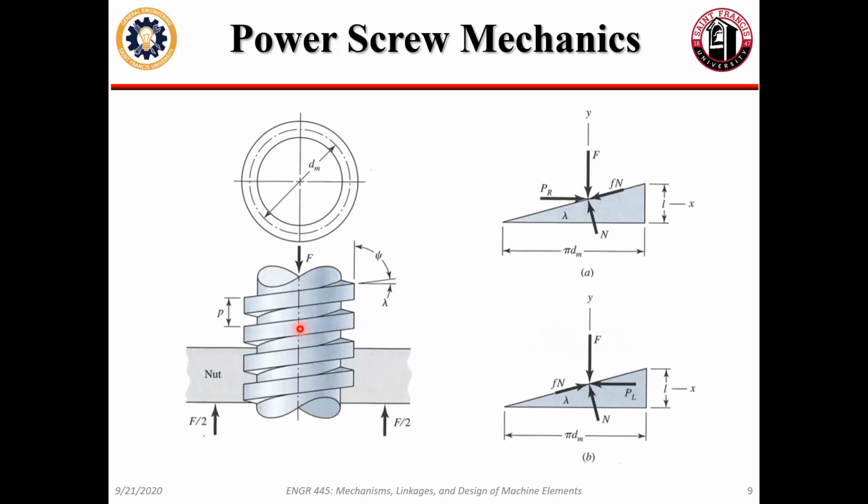If this is a lead screw, we're turning it, right? And we're creating some force because we're moving a nut on it. So we have some nut here that we're threaded into. Most nuts are round or even in some way, and the bolt goes through the center so we don't torque it. So we can assume that the load is evenly distributed on each side of the nut. And by Newton's third law, that also means that we have a thrust force on the screw itself.